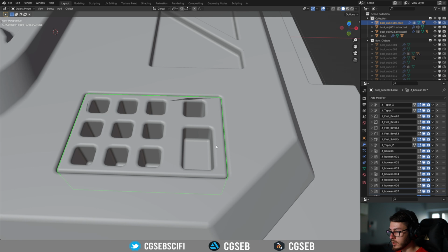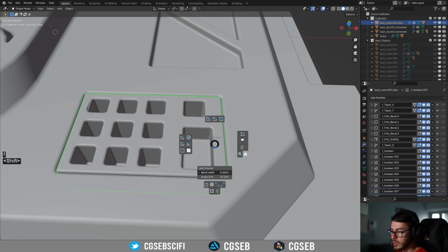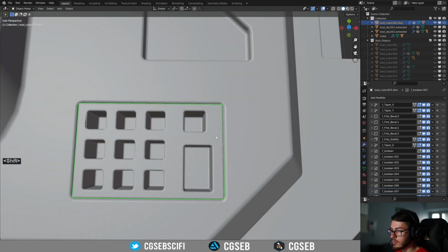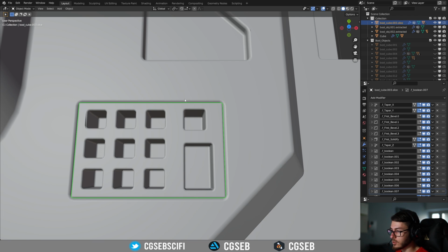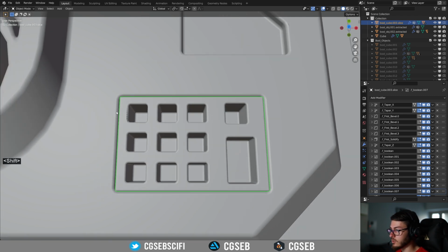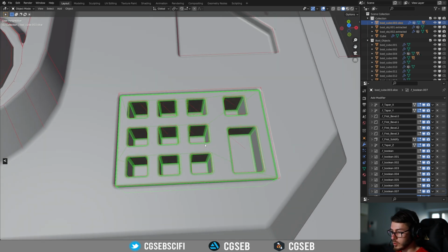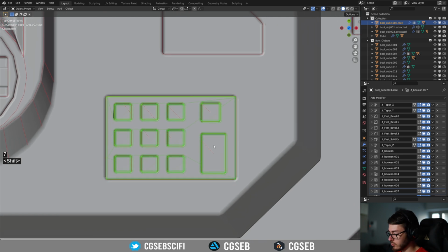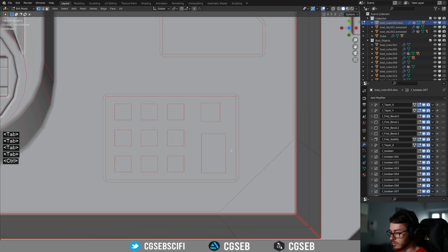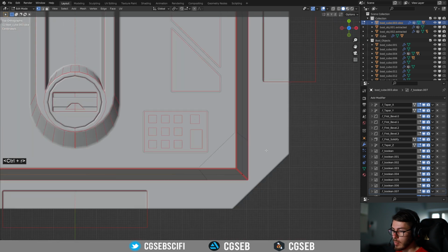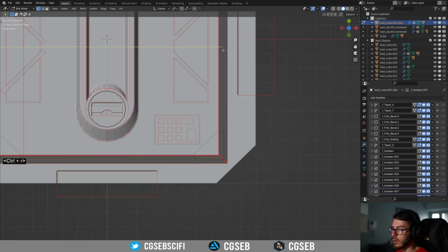We can right click. I'm gonna reduce the bevel. And you see, reducing the bevel is actually fixing this issue and not this one, but I can just show the wireframe, show the booleans, go to the top view, edit mode, and as usual, if you Control R, now you can put your lines and align them directly with the keys.